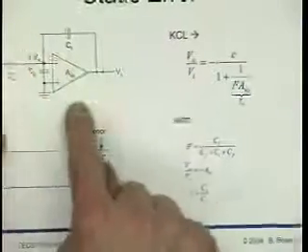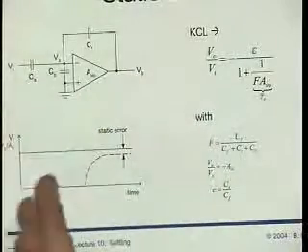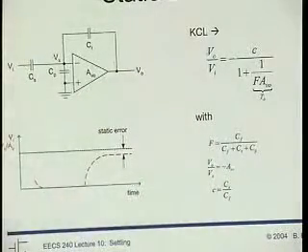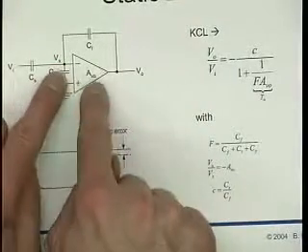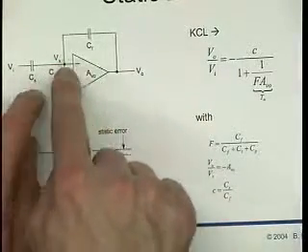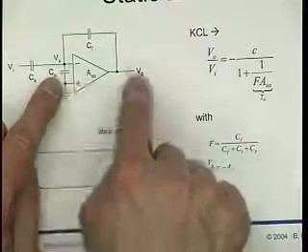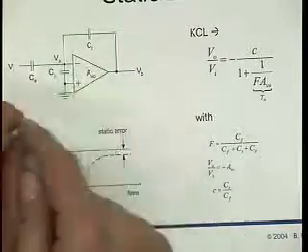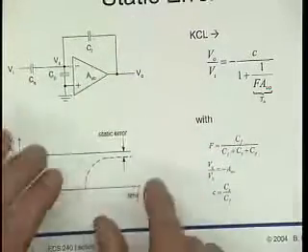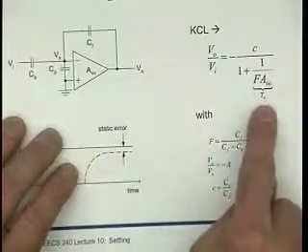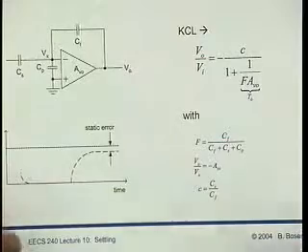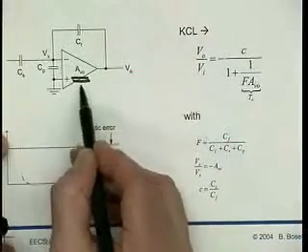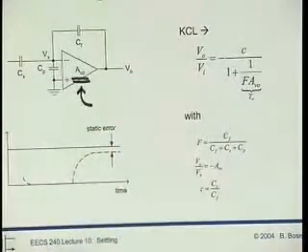So we have this feedback circuit that we assume has somehow been biased correctly using the switches. Right? And now we can calculate using KCL. We can write an equation here, and we also know already that the gain from here to here is AV0. So we have two equations, two unknowns. We can solve for Vout over Vi, and that's the result. Now you've seen that. Also, just a small point here: now you see why I'm so interested in the large signal gain.